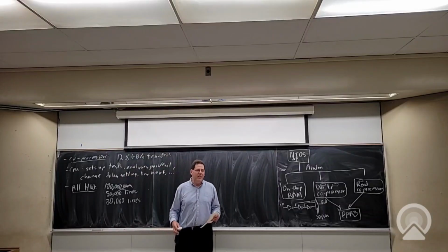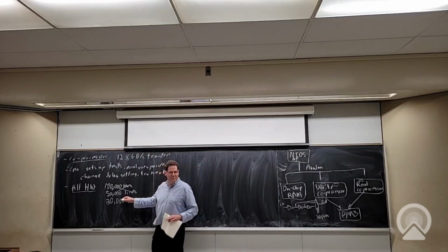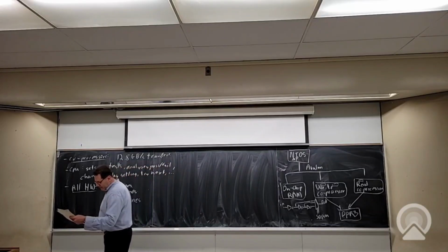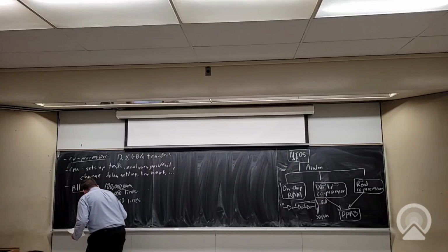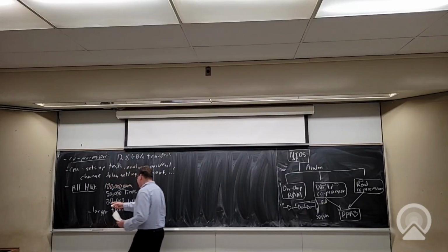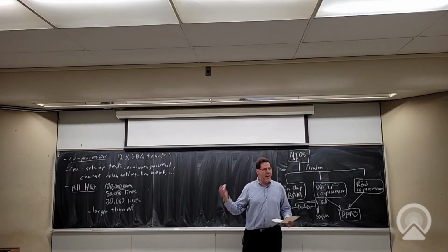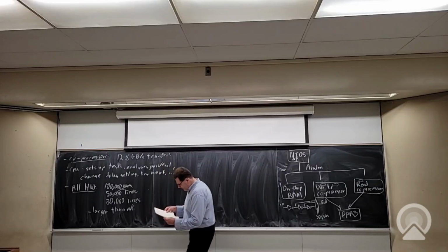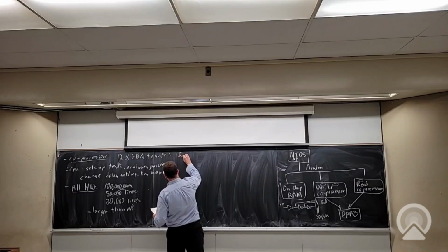Pretty hard to maintain. It also actually starts getting slow. The state machine is so complicated and has loops in it. It was also hard to make the state machine fast enough, hard to modify, and started taking a significant amount of area. So basically this whole thing, not only was it harder to modify and make complicated algorithms, it was also larger than the whole microprocessor. So this would be an example of, as you get into complicated control flow, there comes a point at which you should stop making finite state machines, and processors actually are a really good way to do control flow. Okay, so that's one example where these augmented soft processors can be very useful.